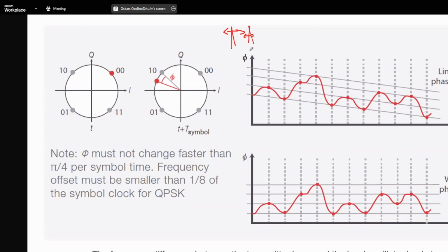My personal experience in lab experiments is that you get very lucky if you get a frequency offset of 0. And if you have very stable lasers, which can be like fiber lasers, then there could be a very small linewidth, in the matter of hertz. Then it's very funny to see that the constellation stays very stable and there's no frequency difference.